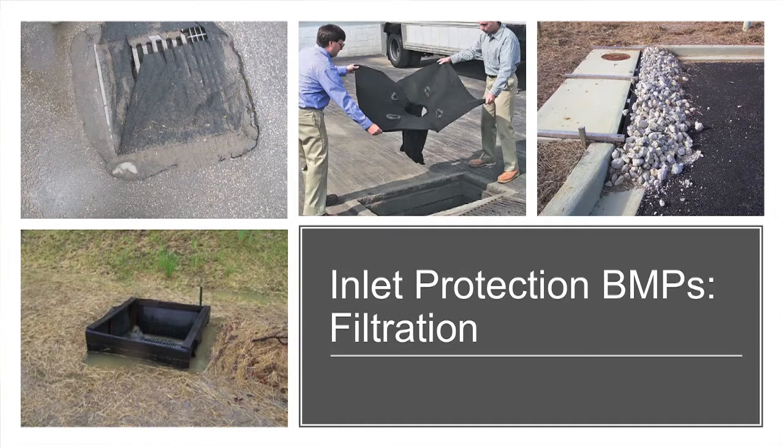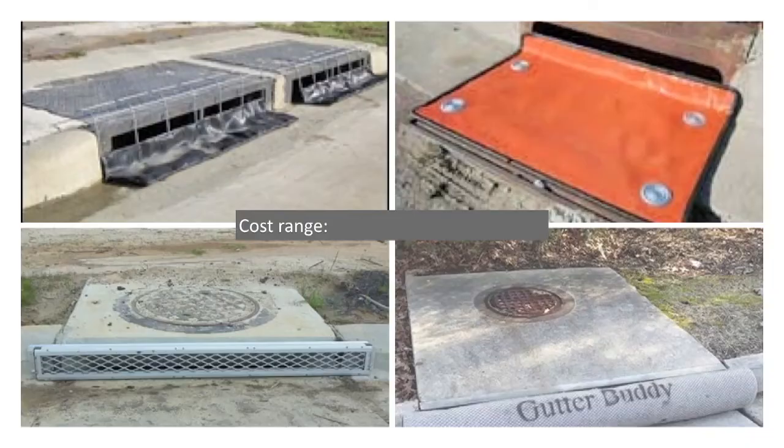Both of these devices here are considered disposable. Aggregate, combinations of aggregate and wood or wire, again, you're allowing the water to filter through by making sinuous flow through all the void spaces, or perimeter controls used as inlet protection devices, in this case, silt fence. Again, the better devices have overflow capabilities or are more engineered for it.